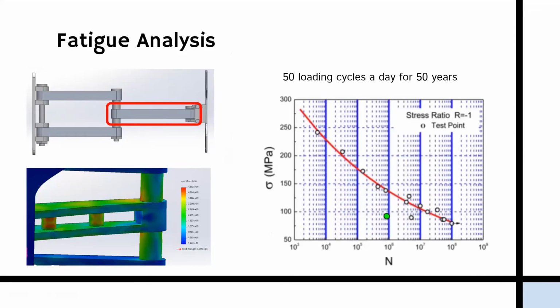From the full assembly simulations, we found that the single arm extension in the top left image experiences the highest stress under all 3 loading conditions in all 3 design iterations. The highest stress on this part was 1.15 times 10 to the 4 psi, or about 80 megapascals.